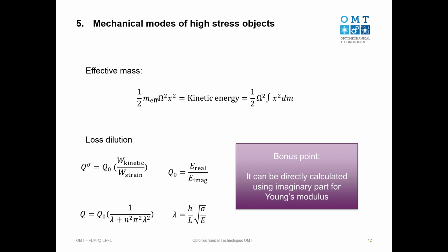So what I want you guys to do today in the exercise session is actually use the knowledge we gained today. We have a stressed film, we have these fillets. Calculate the stress profile, calculate the eigenmodes from it, and then via this integration calculate the Q. See the effect of these fillets: how do they affect the Q? Does it increase it or reduce it? Now we can simulate such a thing. But I will actually stop here.